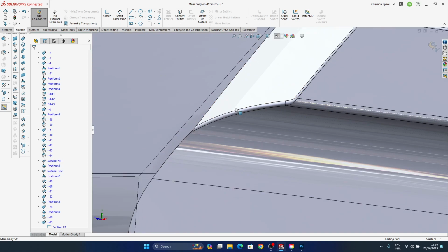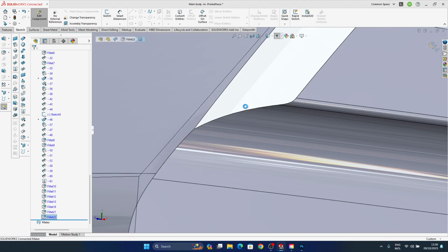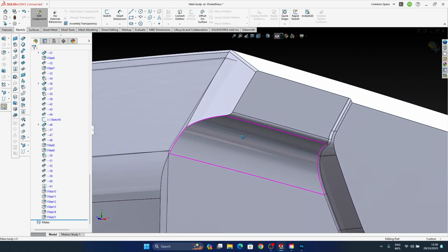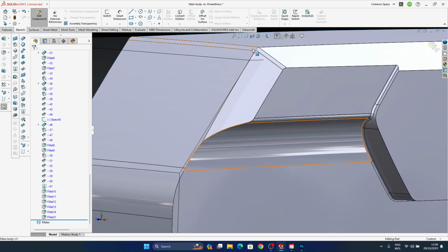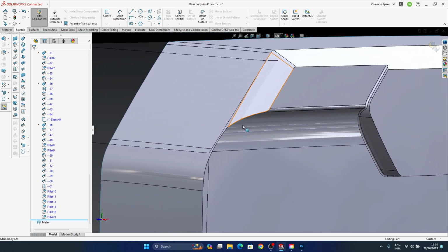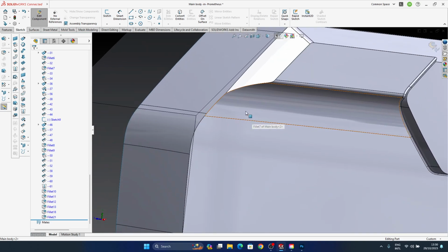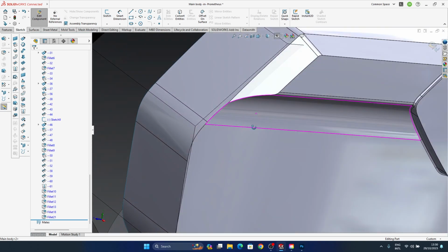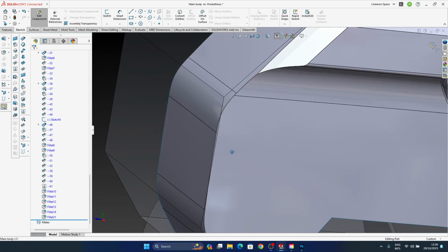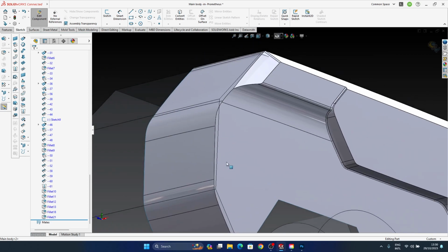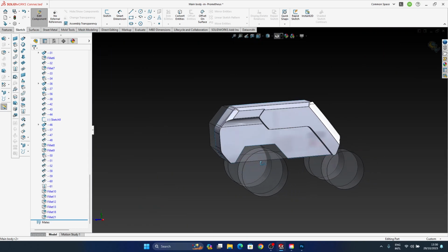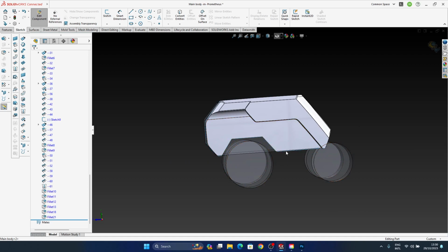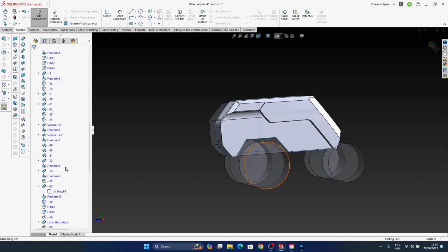Well, I think the first thing to do is to eliminate the fillet that we have in here. We definitely have a junction of three fillets in which this in here would be far bigger. So what we can do is to make a line, make a cylinder, cut the surfaces completely, and join them together separately. So what we can do, okay, but I said before that I want to be sure that whatever I'm using to cut in here is not too high. So let's address that first.